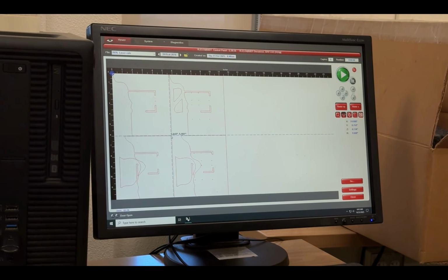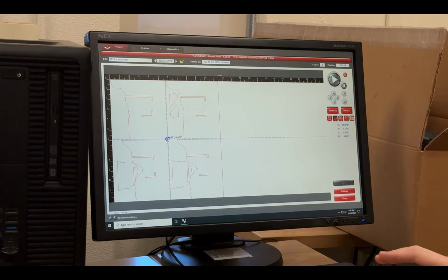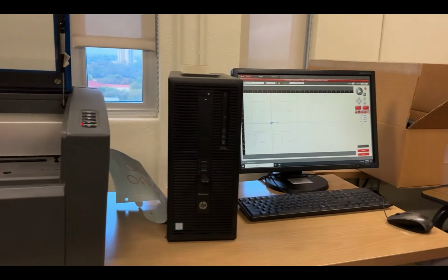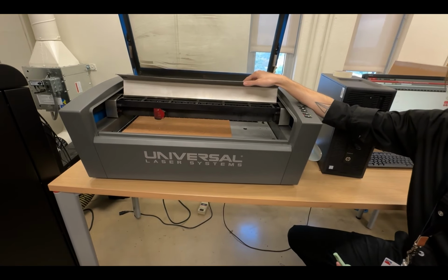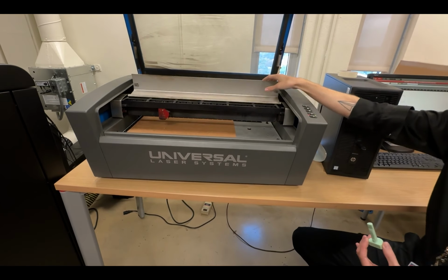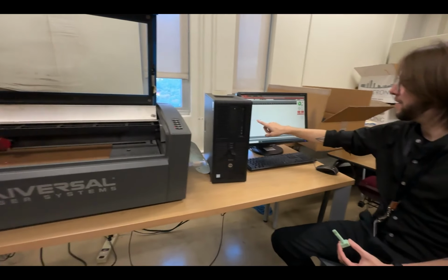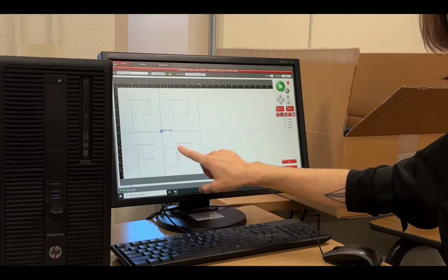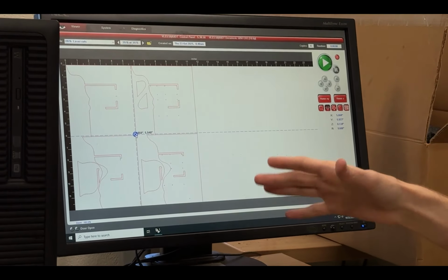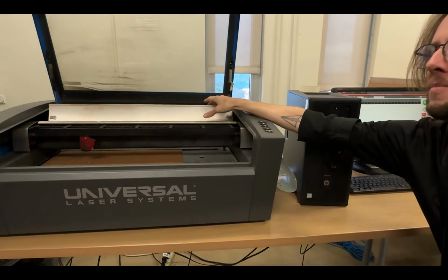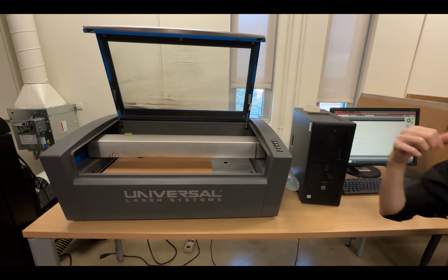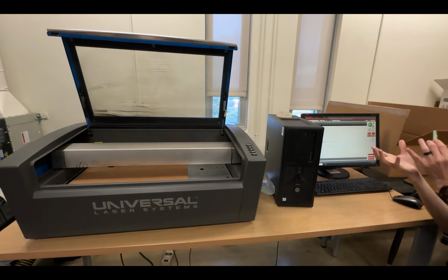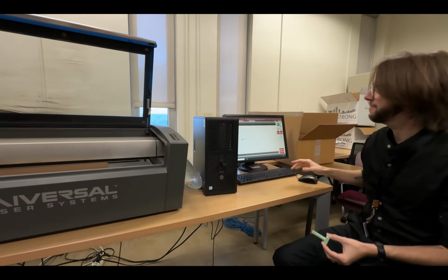So in my case, I'm going to go to the middle of the material, or where I'm about to cut. And of course, immediately you'll see the laser move to that exact position. So that's kind of a game changer, right? Especially if I'm trying to find if certain pieces are maybe outside the range or the extents. So for instance, I open this up just to kind of show you what it's doing. Make sure it's always closed before you click anything, right? The reason I say that is because it can bend itself. It doesn't know that it's open.